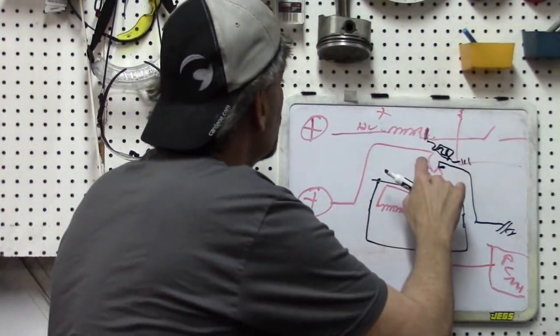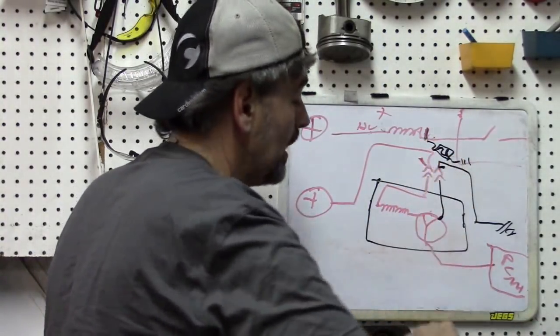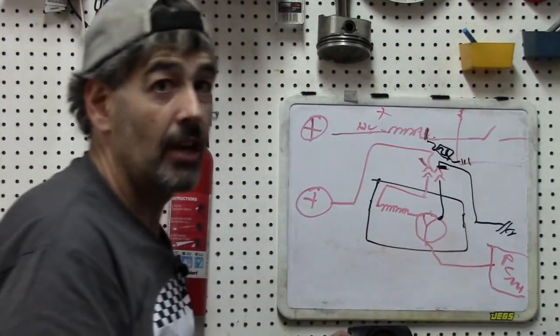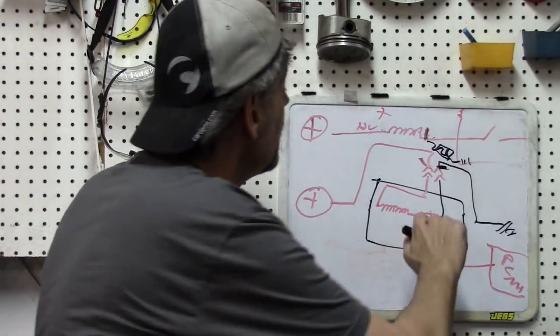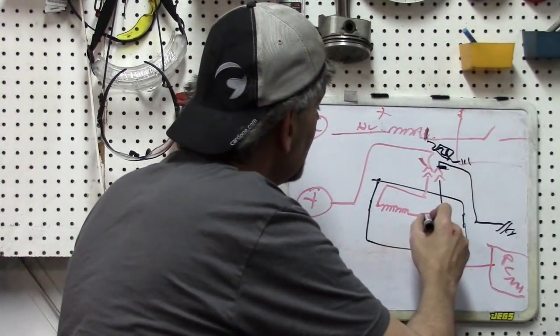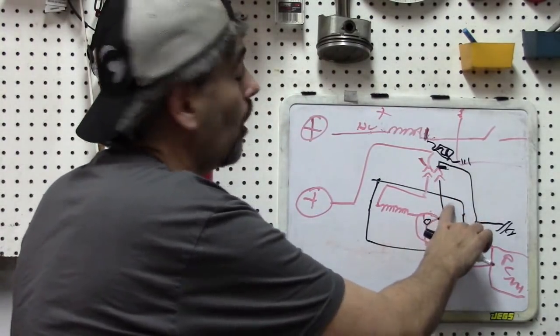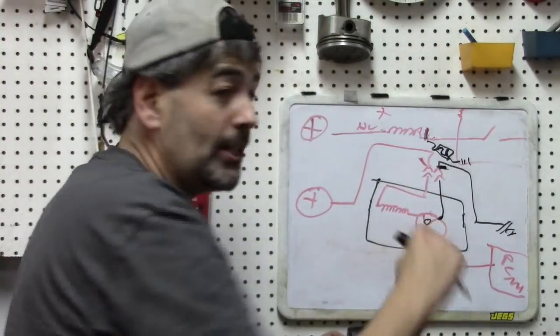Okay? Let's have our scope. We're reading the positive here. We're reading the negative here. The problem is reading the negative here. That's the answer to the question. The problem is reading the negative here because the switch is here. Okay? So we're reading on the negative after the switching occurs.